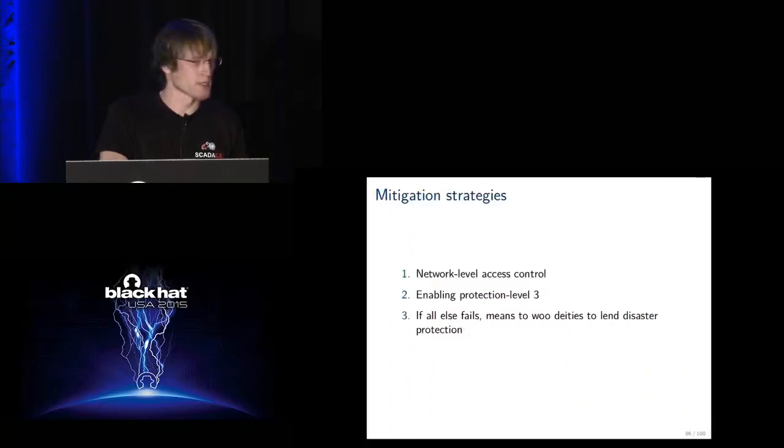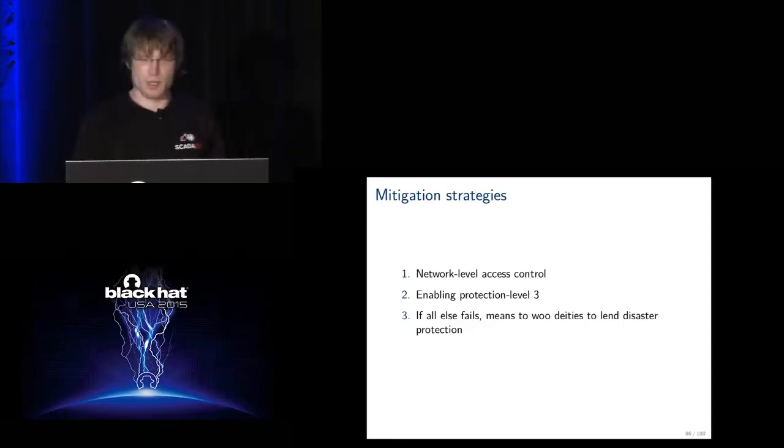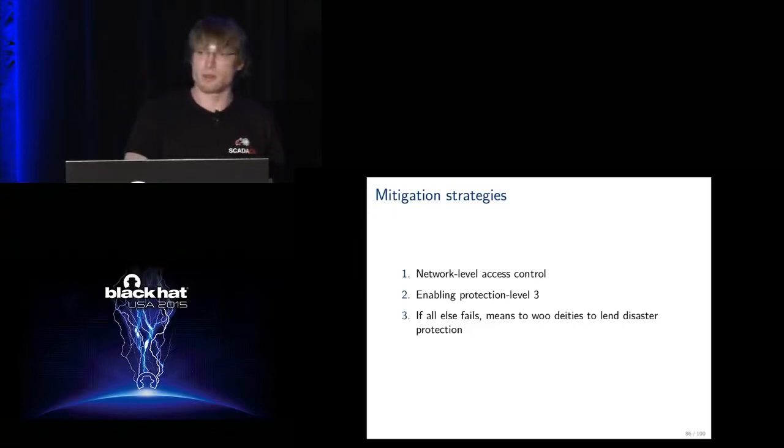There's another way to protect them. Siemens PLCs have a feature to do a read and write protection on this PLC. But you can't upload and download the program, but you can still manipulate the memory of the PLC. You can still run this Metasploit module and stop the PLC, and that's not a pretty good protection. Otherwise, you can stay connected to the internet and hope nothing bad happens.